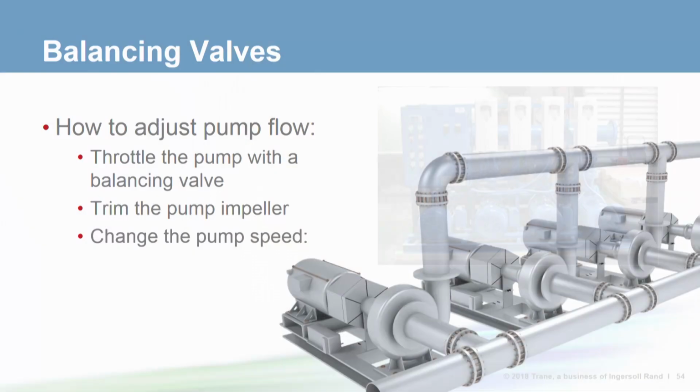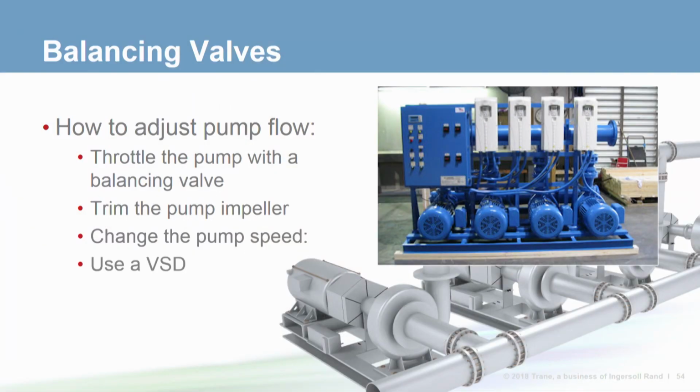Good question. If we include a variable speed drive, we can avoid the hassles of having to disassemble the pumps and have that pump down for hours and days while the impeller is being cut back. With a variable frequency drive, for example, we can simply lower the operating hertz setting in the VFD via the keypad. So this begs the question for existing systems. Should folks consider eliminating the balancing valve near the pump discharge and replace it with a variable speed drive?